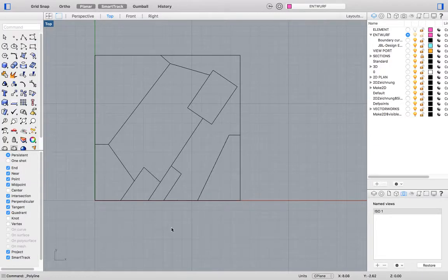Okay. Something I didn't point out, sorry: the snapping features are really important. You must have at this stage these options selected. You can turn near and intersection off. You can turn these off. But the most important is to have end point, midpoint and project selected. We'll turn project off later when we need to use things on the z-axis, which is the up axis, if you like.